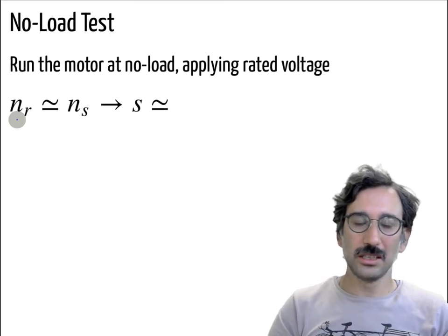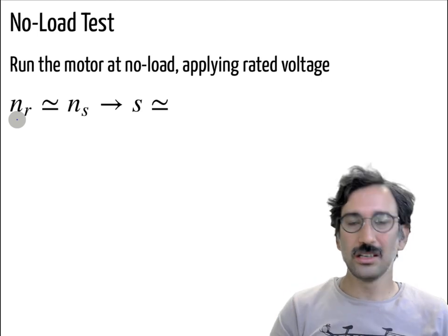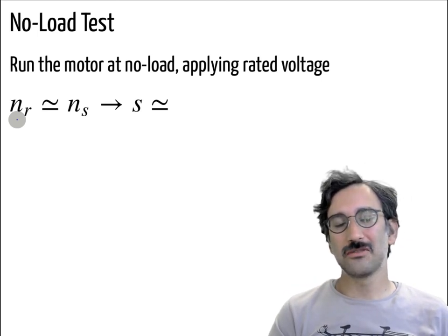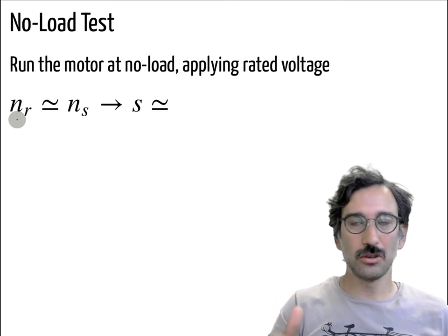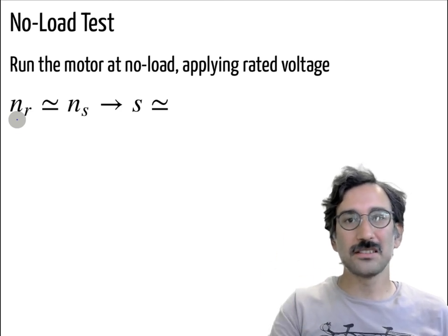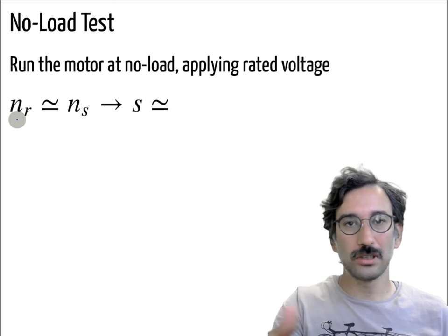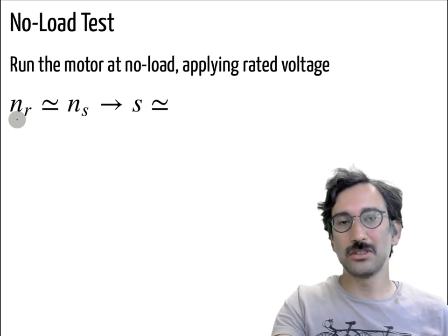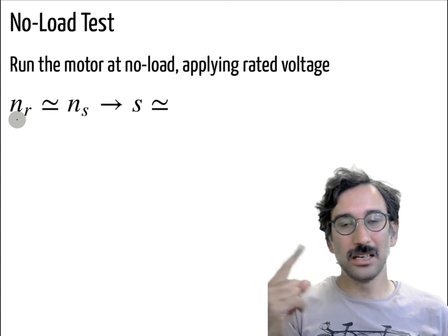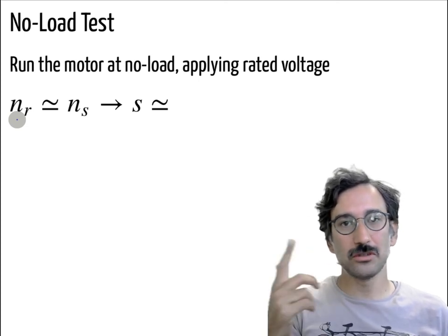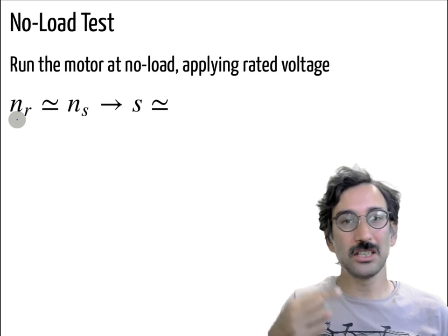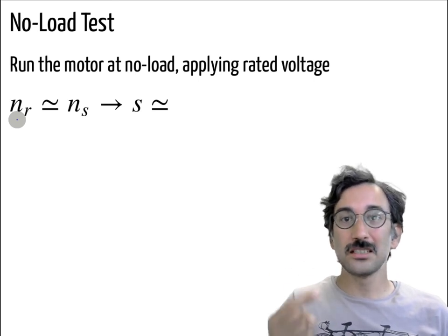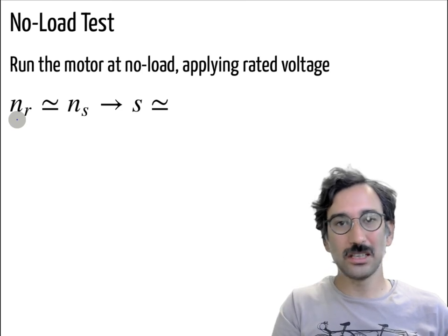For example, if the stator excitation frequency is 50 Hz, you can start from 0 Hz rotor. It quickly accelerates: 10 Hz, 20 Hz, 30 Hz, 40 Hz, 45 Hz, 46 Hz. But at 45 Hz there are still some currents rotating at 5 Hz in the rotor, and that still generates some torque. So it just keeps increasing: 49 Hz, 49.1 Hz, 49.5 Hz.